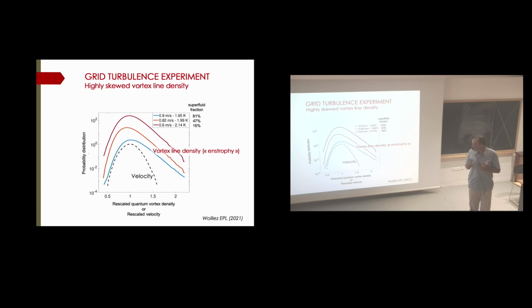The reason is not that we cannot do it. We could, by changing the aspect ratio of the probe, but we have to make a compromise. If we have too good a resolution, the quality factor is large, and that means the time resolution is poor. So we always make a compromise between the mean velocity of the flow, the size of the probe, and the time resolution that we want, and that sets the resolution.